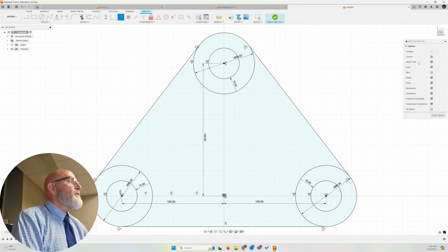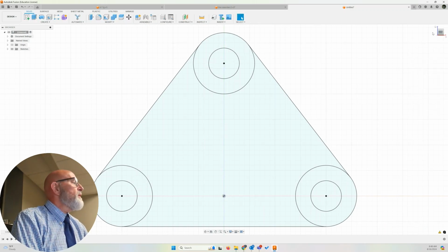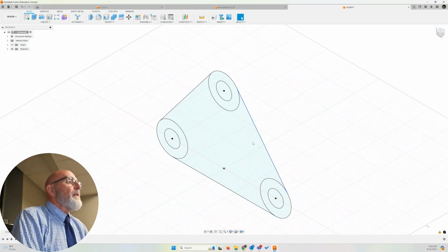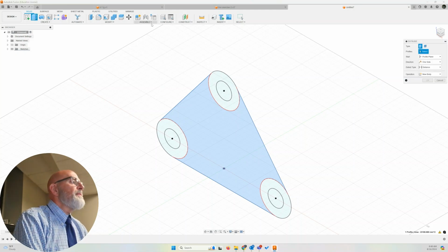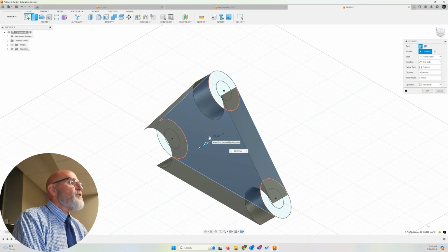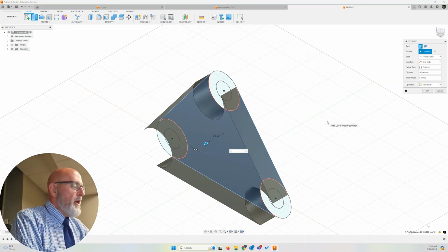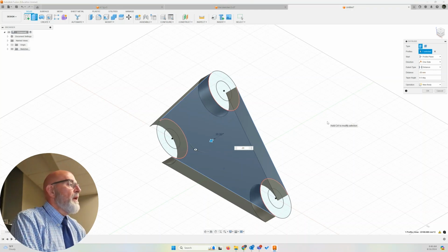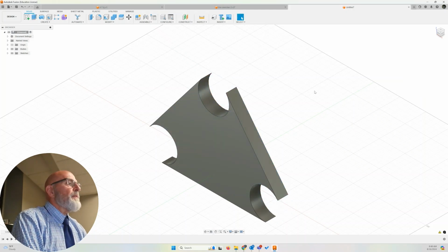All right, let's finish sketch and get our extrusions done. Home position. We're going to first extrude the main body. So let's go create, extrude, keyboard shortcut of E. I had the body selected. I want to come this direction. We're going to go negative 20 millimeters. And new body, click OK. All right, so that part's selected, but my sketch went away.